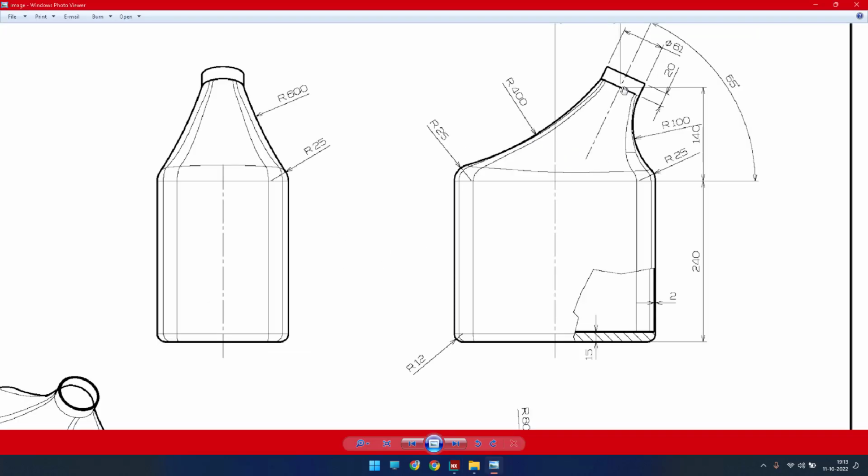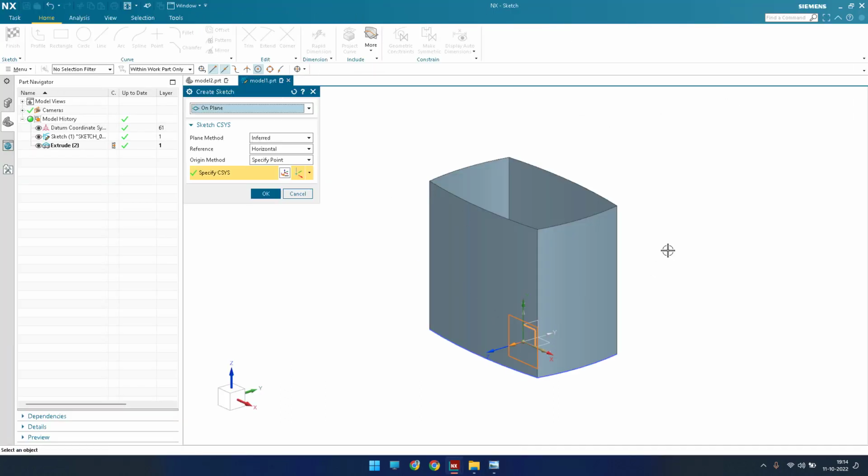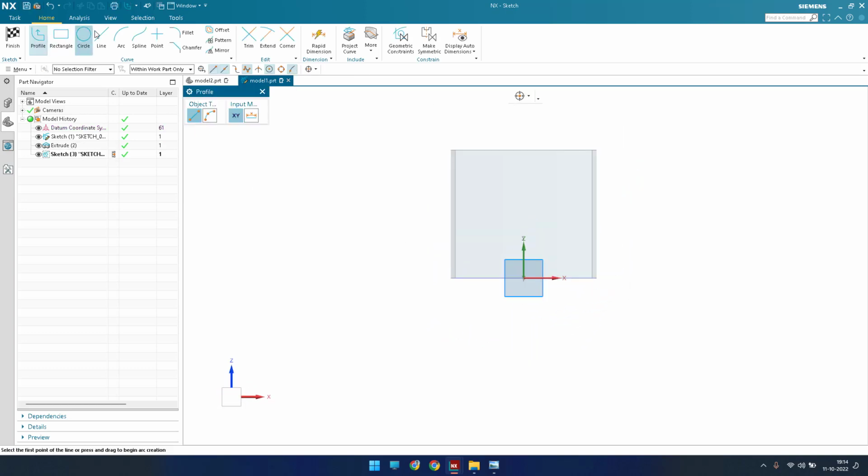Now I'll make this circle. As you can see here, this is the cylinder we need. We have to create this cylinder, and then make curves to this particular base, and then make a through curve mesh. In order to do this, I'll create one simple sketch for reference. I'll go to the sketch environment on this plane, and here I'm going to draw two lines. This is one line, and there is one more line.